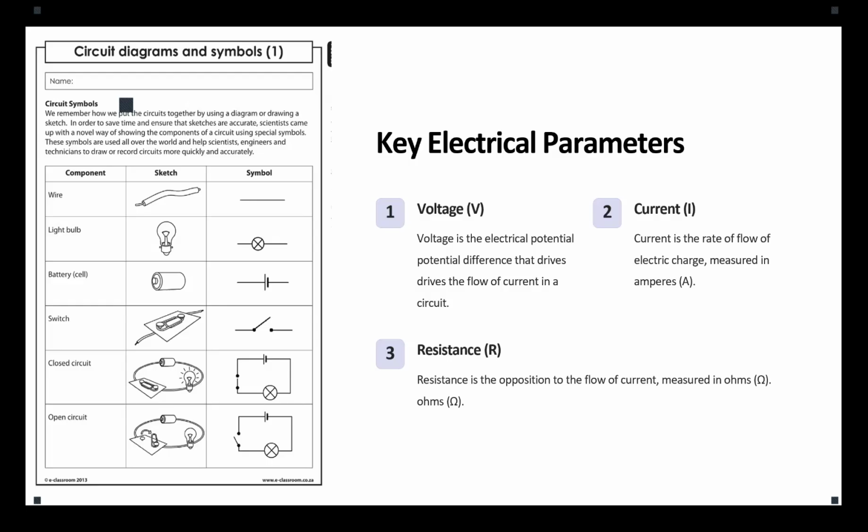Okay, so remember that. And there is another point: when we talk about the movement of the charges, the general assumption is that we consider the electrons as the charges that move energy. Okay, but I want you to know, and this is kind of a misunderstanding, the direction of the current that we show in the circuit is not the direction of the movement of electrons, it is the direction of the movement of the positive charges. Okay, so if the direction of the current is from left to right, that means electrons are going from right to left. It is because of the definition. Centuries ago, they defined the current as the movement of the charge. That was before they knew the electron exists. Okay, so they considered the positive charge as charge and negative charge as absence of positive charge. So this is the reason.